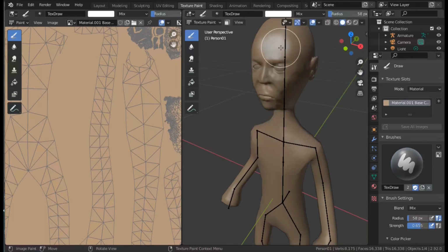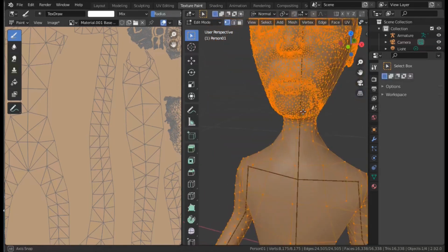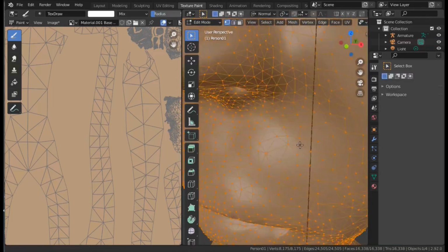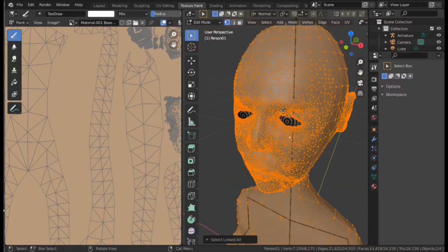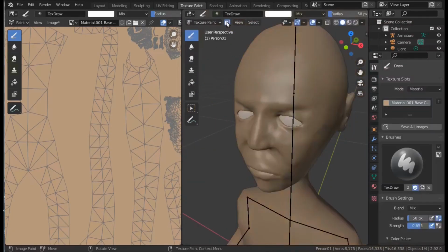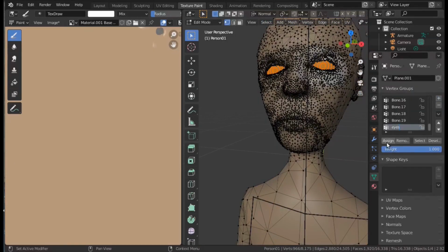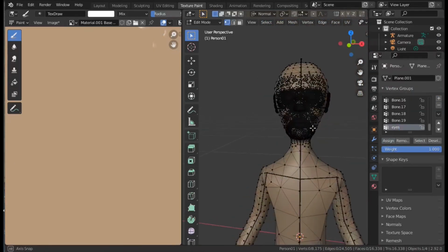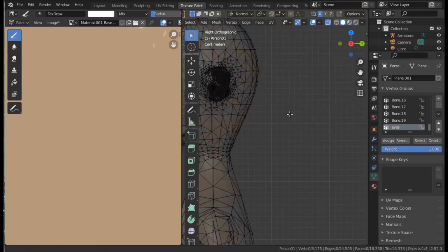But the first thing, rather than painting onto a specific texture, in material mode we can select the different contributions to the material. So choose base colour and it will give you the options to create a texture, and click on alpha. We don't need an alpha for this. We can start painting, but choose a base colour which is approximately skin colour. And you'll see in the UV, which has been unwrapped on the left, that the colour filled the whole of the texture there.